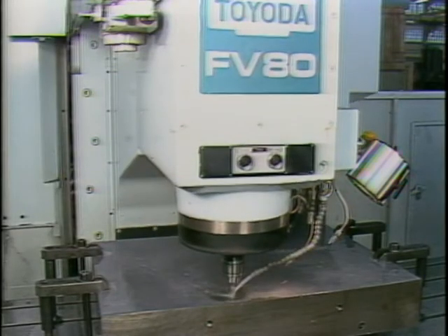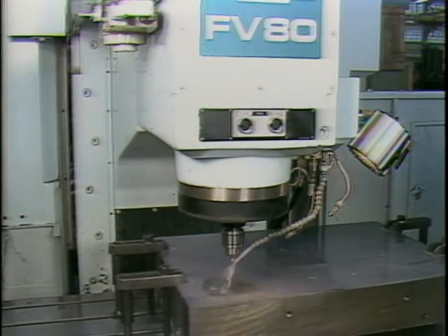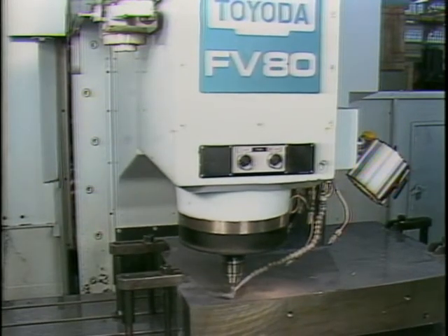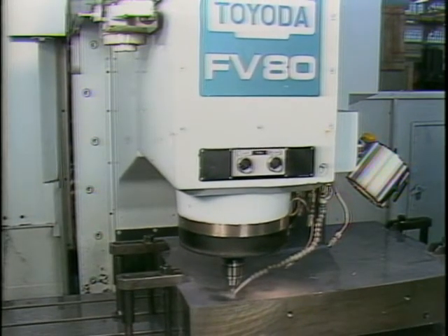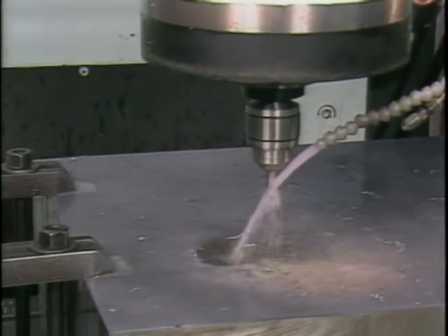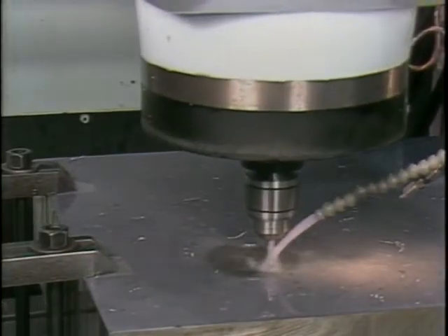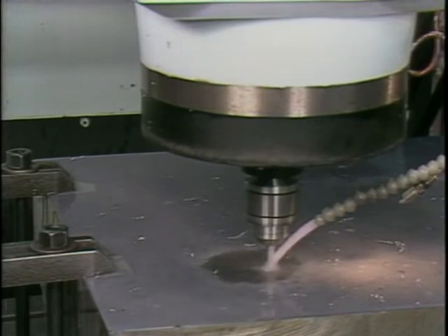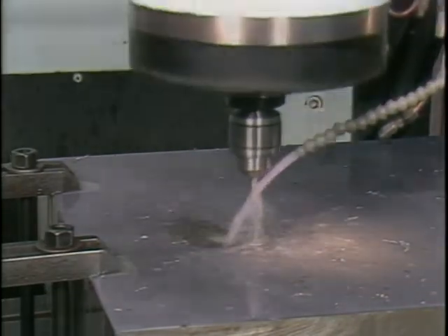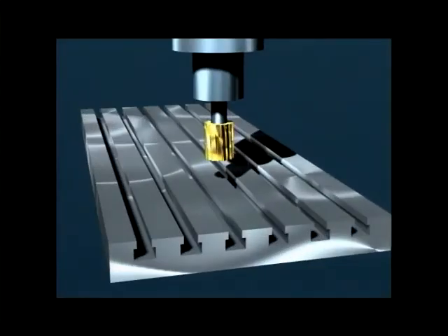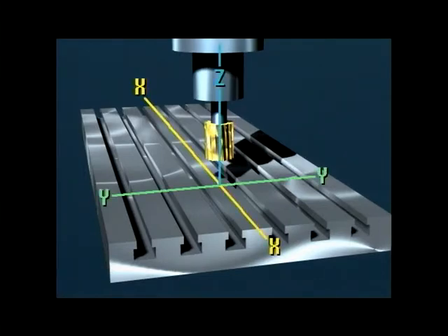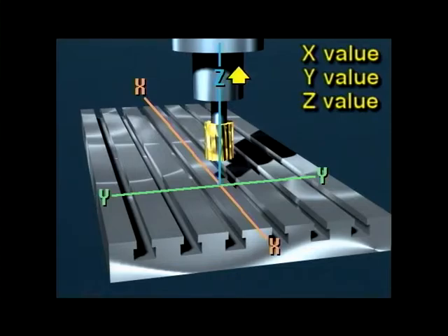This three-dimensional coordinate system is the same coordinate system used on CNC machining centers. Since it allows any point in three-dimensional space to be located and defined, this coordinate system permits controlled movement in any direction to any location. Typically, the primary axes on machining centers are labeled or addressed as X, Y, and Z. Coordinates in a three-dimensional grid require 3 values, one for each axis or dimension.